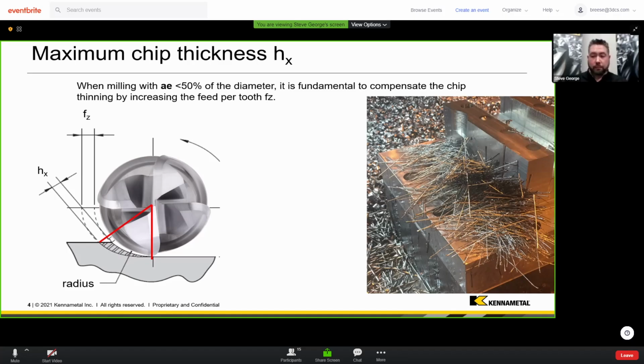High speed cutting is going to be a little bit the opposite. It's going to be a lot of what we're talking about on the dynamic side of small radial depth of cut and increasing the spindle speed because of the drop in temperature to get some speed back. The biggest difference, in my view, between HSC, high speed cutting, and HEM, high efficiency milling, which is more what I'm going to be talking about, is that it combines the high speed cutting and maximizes the axial depth of cut.